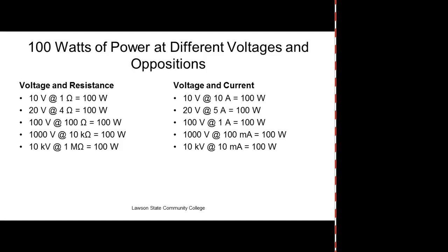Now you've got to understand, you say, well, I'm going to go home and wire all my outlets for 240 volts. Loads are designed around a certain voltage. So your vacuum cleaner and those light bulbs are designed around 120 or 115 volts. If you put a 115 volt load across 240 volts, it's going to blow just like that. If you put your 120 volt vacuum cleaner across 240 volts, it's going to smoke.